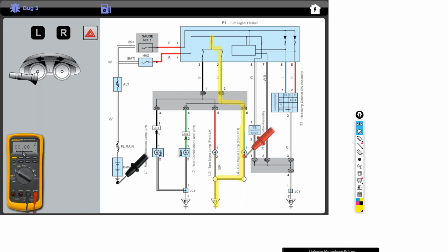If it was high resistance, you could have a corroded ground or something like that causing this issue. Now, corroded ground would be something more like 4, 5, 6, 8 volts, 9 volts. I have seen that. Sometimes it's like 9 or 10 volts. The bulb's not on, or maybe it's extremely dim. That would be high resistance, and the voltage would be divided between the bulb, which is the load, and the resistance in the ground or wiring or whatever the connection.